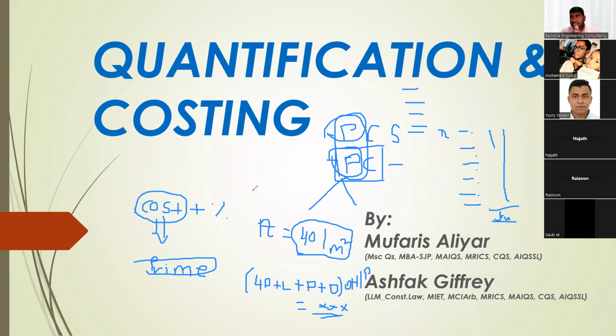So that is one reason that a PC rate comes in the BOQ. So what is the one reason? There is no detailed specification. We don't know who the supplier is, but I know only the unit rate of the material. In my mind, I know only that I want to spend 40 dirham per square meter of this tile in this project. So I fix it. So there is another challenge. That is the challenge we face, based on my case studies.